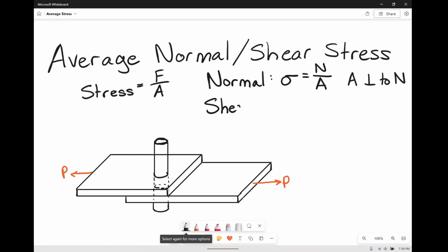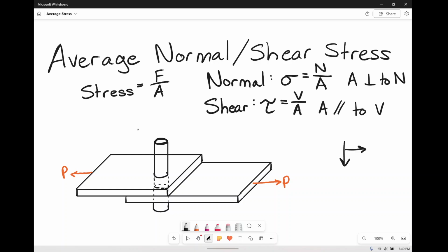Our second type is shear, and shear is tau. So it's a very curly looking T there. And it is the shear force over the area. And again, which area is that? That is the area that is parallel to the shear. So effectively, when we were drawing our normal force and our shear force off of our usual cross-sectional area, they were both talking about the same area, and that was the area of that face.